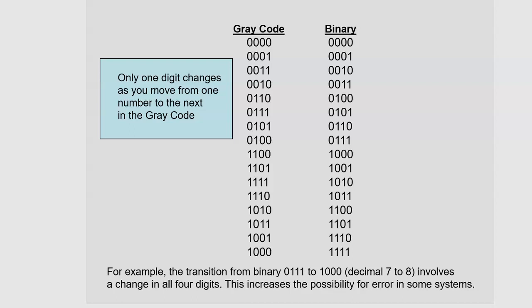We can move those bits around from one place to another because we have these things called shift registers. So I can have a binary number, a voltage, and I can turn that voltage into a pulse, and I can move those zeros or ones around the circuitry in the digital device. Well, sometimes mistakes happen. You might have a binary number, say, this number right here, 0, 1, 0, 1. That's 0 volts, 5 volts, 0 volts, 5 volts, using the amplitudes that we talked about in this class.